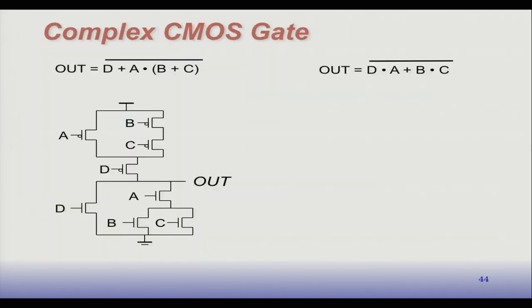You looked at NAND and NOR. And this was one example that we had here. And we said that in order for these two networks to have this property of being complements, they're the dual of one another. If you think of this as a graph, the pull-up is a dual of the pull-down, right? So the simplest way to think about designing these gates, if you look at the logic function we're trying to implement here, the ANDs and ORs give us an indication about transistors being in series or being in parallel, right?